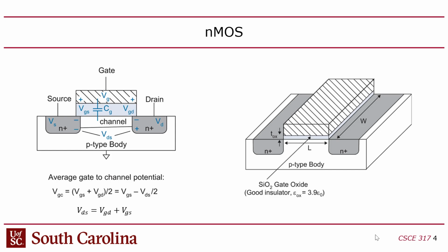So Moore's law says that the area, length times width, is halving every 18 months to 2 years. You might be saying, it's weird, because they went from 180 to 130 to 90 to 45 nanometers. The length was not halving, right? But that's fine because it's the area that's halving with Moore's law. Generally speaking, the minimum length and the minimum width are scaling down at the same rate. You guys with me?